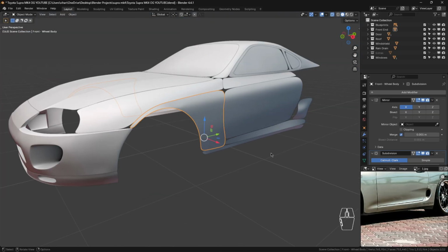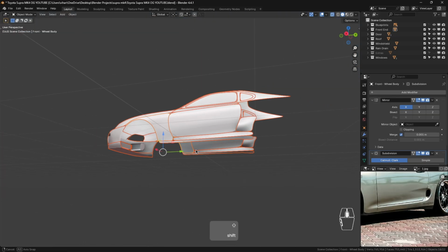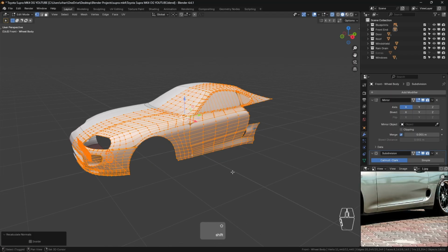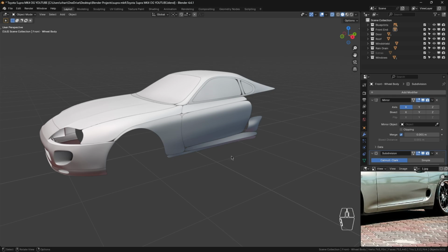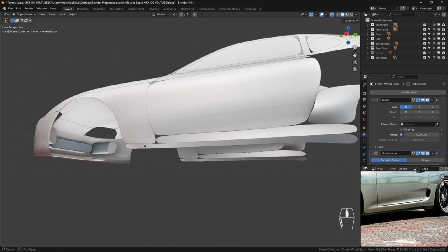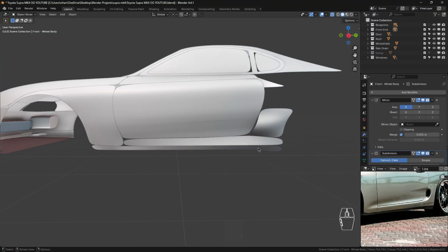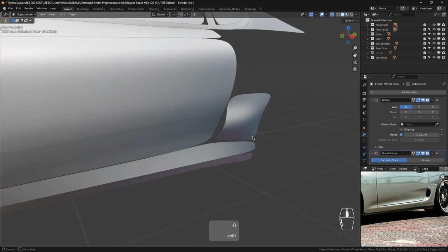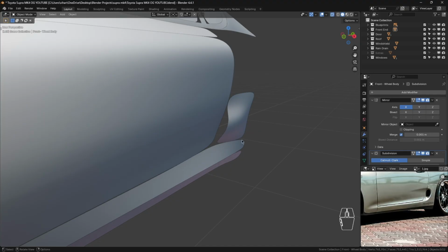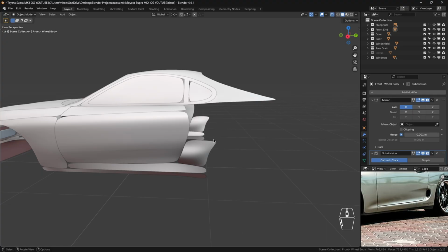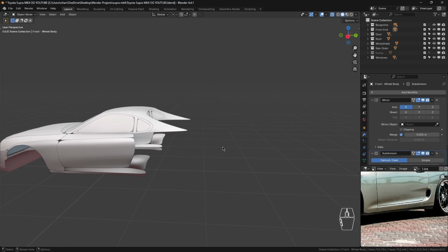There we go. And just press A, Tab, just press A again and Shift N. That's just gonna be adjusting our normals again for the entire car. And there we have our sill there. So our door sill is ready. It was not a major part, but we're gonna be doing major parts for this one, this vent that we have here. And the next part is going to be our big chunk of back end right here.